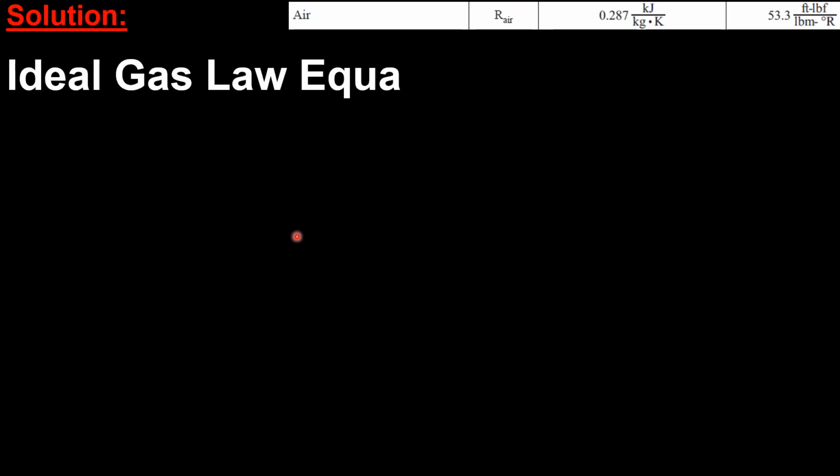All right, so in this slide, we want to use the ideal gas law equation, and we will use it for state 1, or the gas at 0 seconds, before the gas starts to leave the system from the drilled hole. So this is the ideal gas equation. Here the pressure in blue is given. The V is given. We need to find the mass.